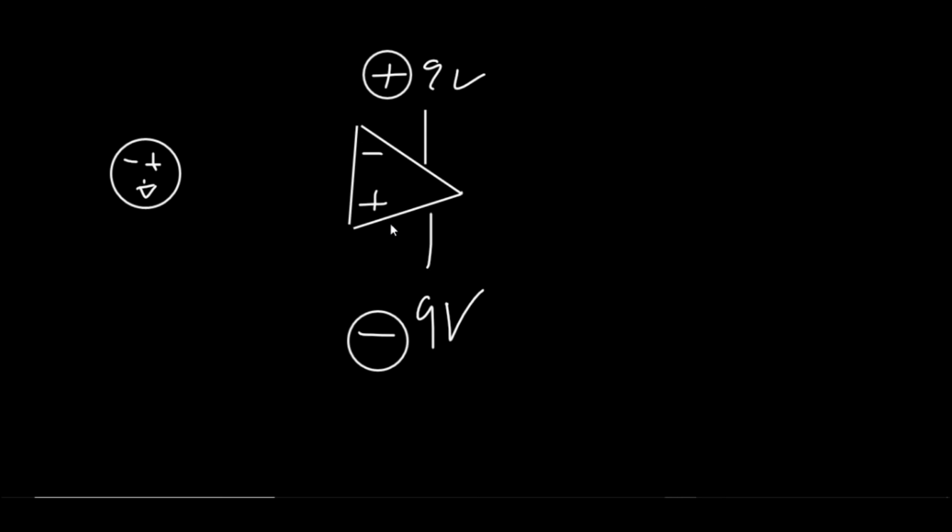So that makes the power supply complexity increase. Though again, they're really good at making differential amplifiers as they have two inputs. So the input coming from the microphone preamp output could directly translate into the inputs of this op amp. Because we have to remember here, what I want here is unity gain.